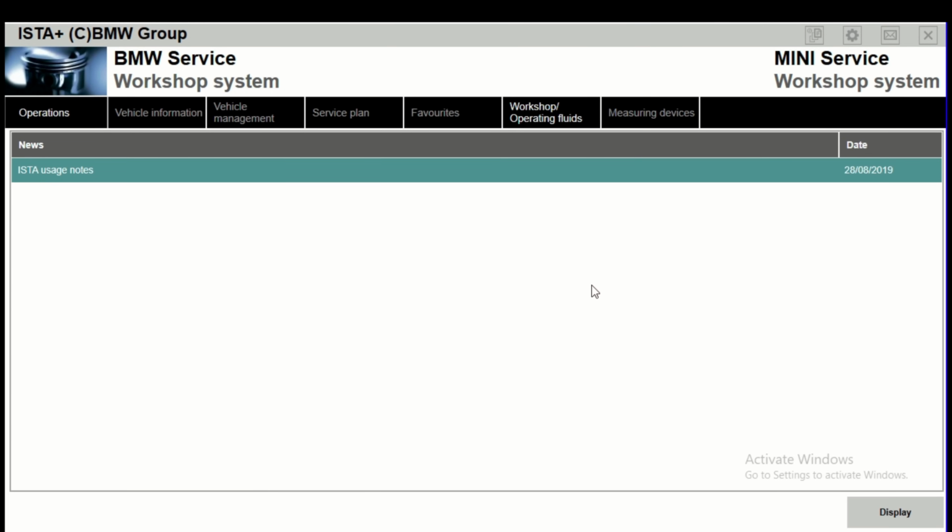If you take your car into BMW, a lot of you go in there saying, oh, you want your car updated, you want this, you want that. They tell you they can't do it, and that's purely because BMW, when you go in there, cannot just update one specific module, and I agree with them on that. I know because I do this. You cannot go to BMW and just say you want your DME updated. It does not work like that. ISTA-P will not let you do that.